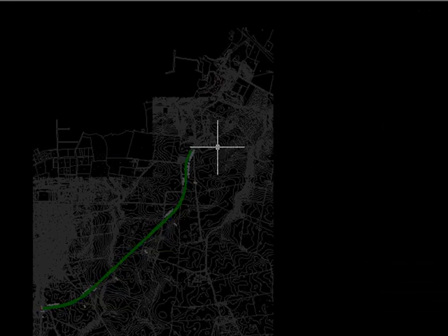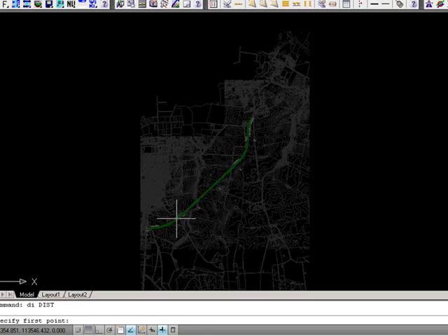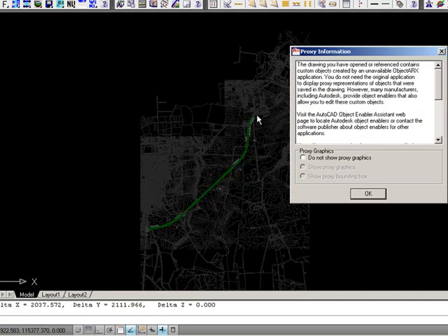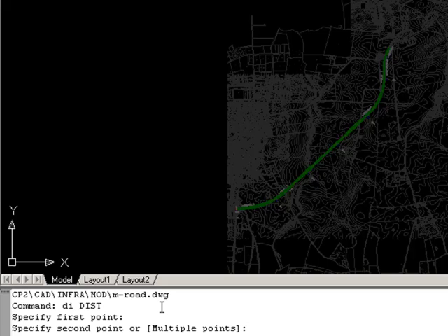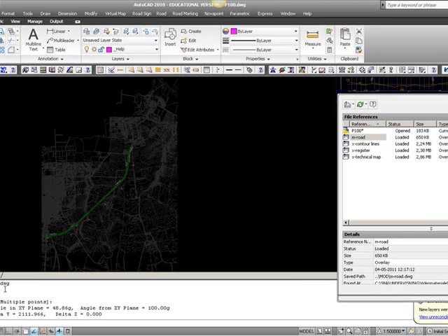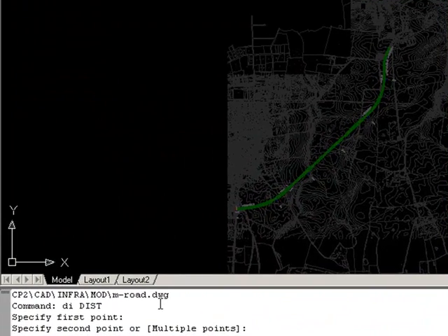Now the first drawing I'm going to set up is a 1 to 5000 of the road. First of all, I need to know how long it is. It's approximately 3 kilometers. 3 kilometers in the scale 1 to 1000 will require a paper more than 3 meters in length. In 1 to 5000 the paper will be 5 times as small, so I need a drawing area of at least half a meter. And to this I need to add one complete A4 sheet for drawing information, legend and stuff like this. So in this case my paper will need to be 840 millimeters in length, and probably I can do with just one A4 in the height. So this is what I'm aiming for.